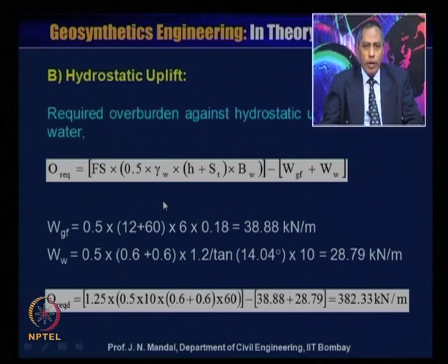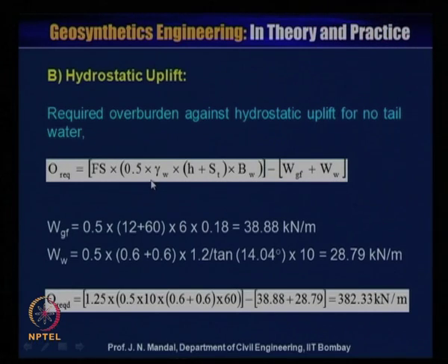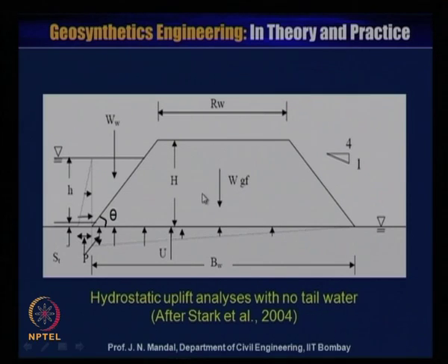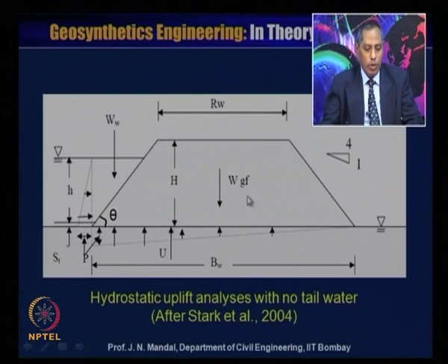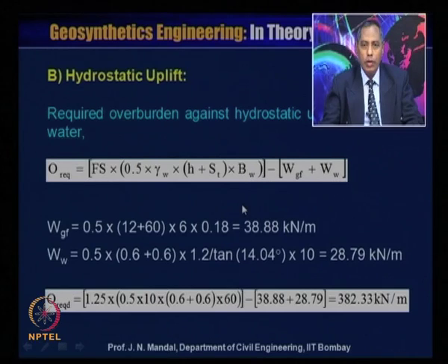So we know this is the unit weight of water, you know what H and St are, you know what Bw is, the base width, and Rw is the road width, and you know Wgf, the weight of the geofoam, and then you know Ww. Now you have to calculate Wgf, that means the weight of the geofoam.